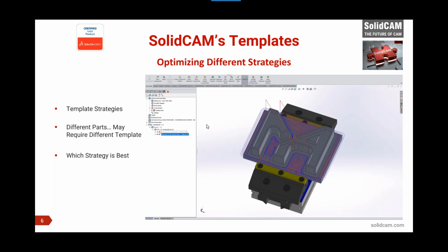And so this style of using a template can also offer you the ability to test things, okay? One of the things we teach when we're teaching iMachining is that when island moating consumes more area than the spiral morphing in a particular region where it's working, then sometimes it can be more efficient to not use the island moating, okay? And so you may need to try them back and forth. You're going to get used to it after a while. Doing this more often, you're going to kind of see the geometry alignments of parts and kind of pick and choose which one you want.